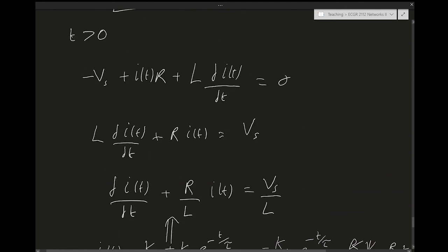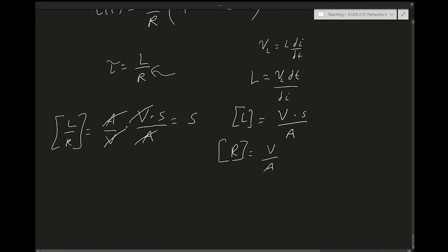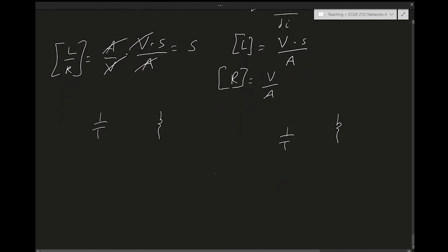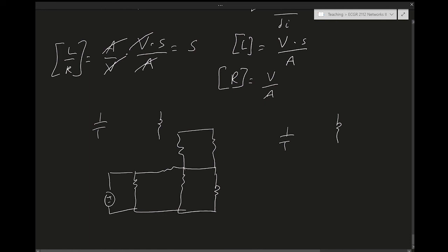So we solved basic first order circuits with an inductor and with a capacitor, right? And that's the best we can do with a first order circuit, because if I have a circuit with two capacitors or two inductors, I end up with a second order circuit. So it's outside of the domain of a first order circuit. But we could go further. We could solve more general circuits where we have an inductor and then a network of resistors, let's say, or another circuit like that, but with one capacitor.